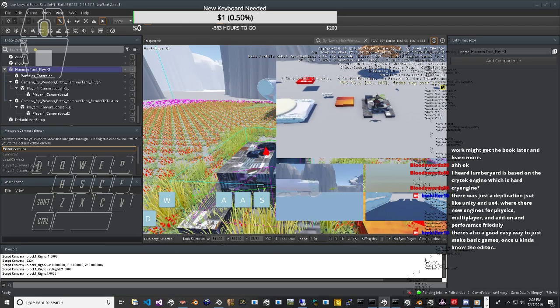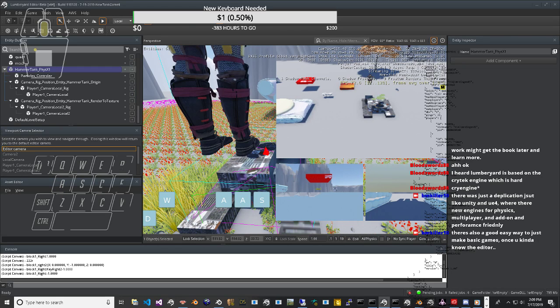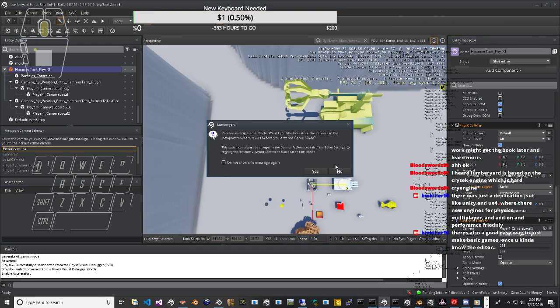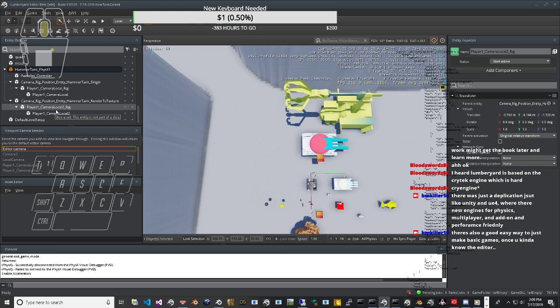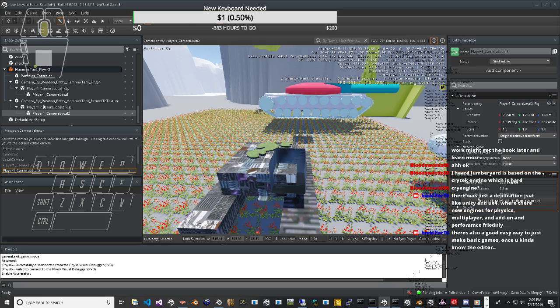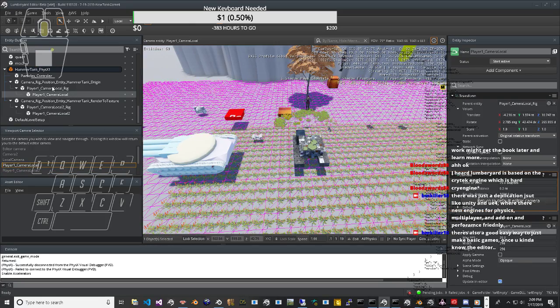Let's mentally follow a piece of tread around as the wheel, not necessarily the tire, turns at a constant radial velocity. Imagine a plug of yellow rubber embedded in the tread, so that you could visually track it or photograph it with a movie camera or strobe system as it moves around the circumference. The rubber of the tread does not travel at constant speed, even though the wheel supporting the tire does. At the top of the tire, the radius is almost exactly r, the unloaded radius, so the tread moves with tangential velocity v/r times r.